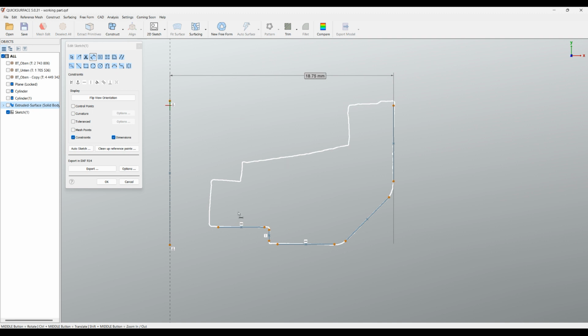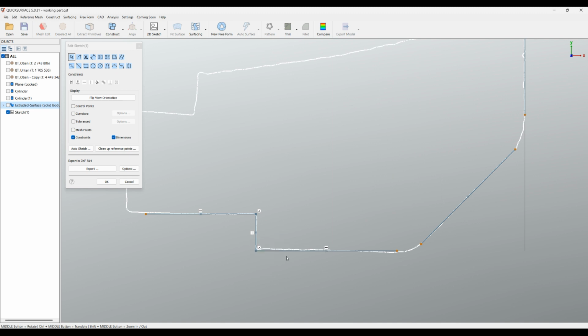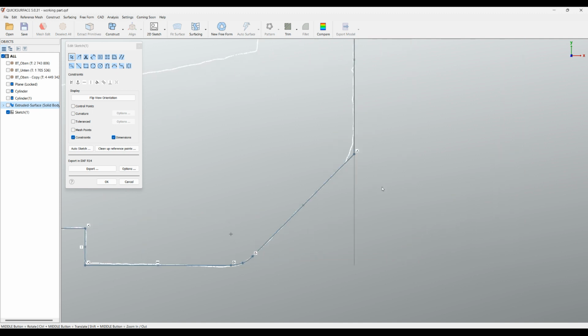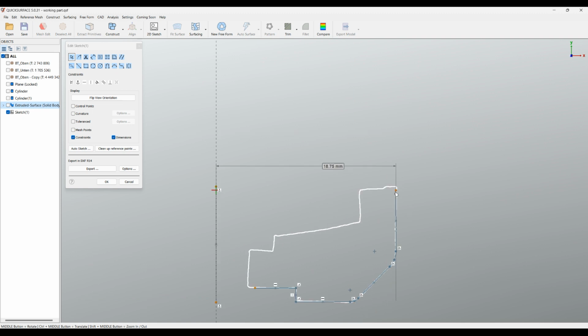I'm going to start intersecting these. How it works, if you just hold the control key and brush over the corners, it automatically will intersect them. If I brush them again, it actually will make even a fillet. Let's intersect these and brush so I can get this rounded. In this case, what I need is just to have this much bigger, because I will need these for the Boolean operations, and I will just try to close my sketch.